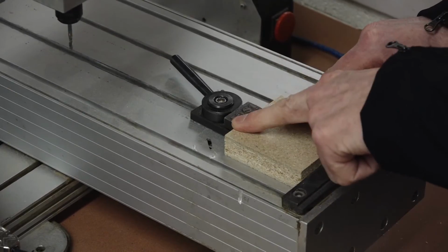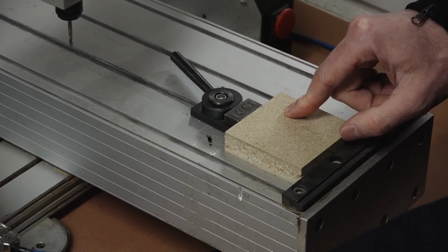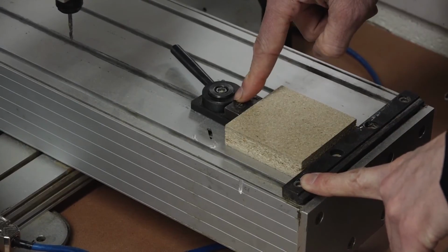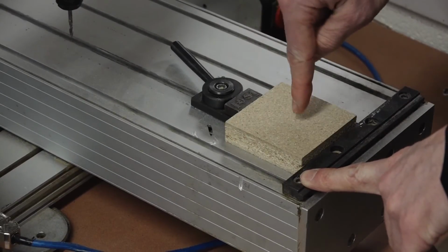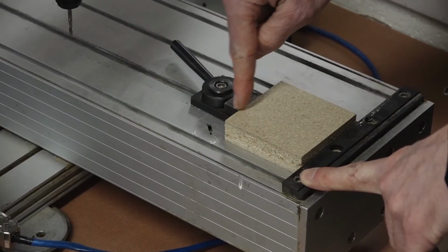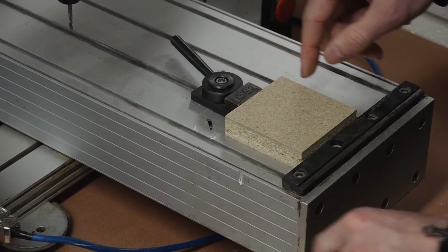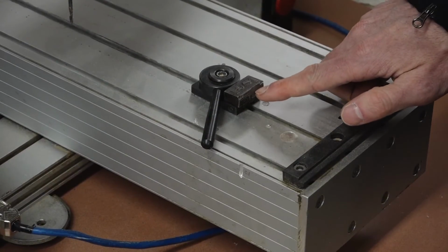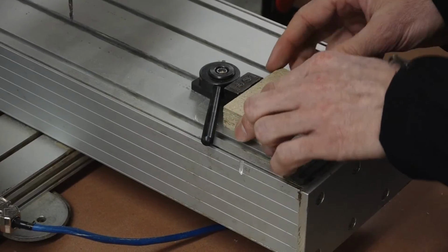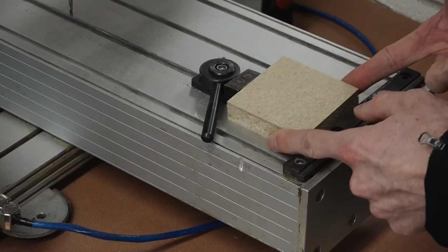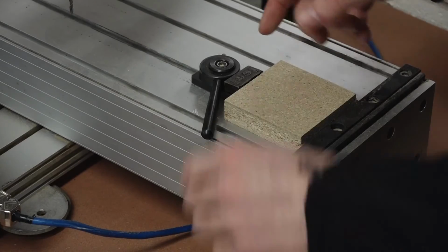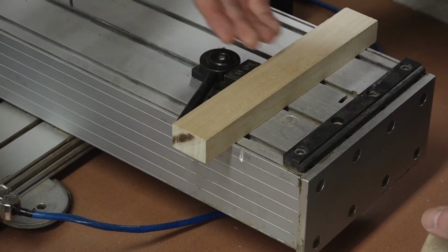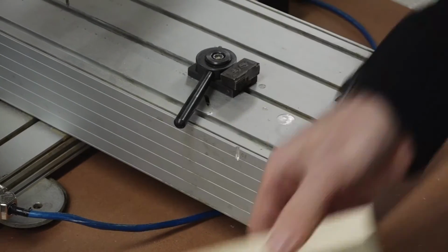Like I said, if you're going to the edge, you'd want to put some kind of block between this metal piece and the clamp, so that when the bit is machining off to the edge, it doesn't machine into the clamp. You can see that this has been machined into probably multiple times. So we want to try to avoid that. It's always best to have it clamped in the center, but this is offset, so if you have a piece this wide, you'll probably be on one side of it, not right in the middle.